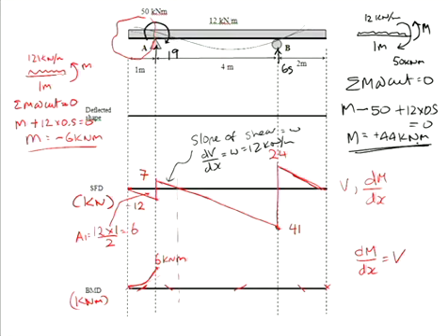So I actually love equilibrium. Equilibrium will tell you the sign, it will tell you everything. Because it's a plus, you know your bending moment value now suddenly steps down to 44, and that step there, of course, is equal to 50. So, according to our upwards-downward slope, my bending moment continues to move down.